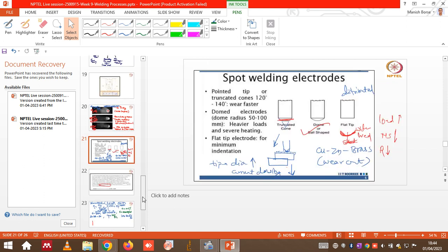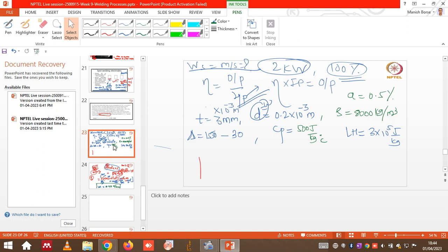In most cases, only volume is important, because of how we have to manage the volume calculations. Sometimes they already give volume or energy in joule per mm cube or joule per meter cube, like melt energy, where we have to multiply it with the volume. But in certain cases they give cross section area and we don't know the thickness, but welding speed is one of the variables, just like in this numerical, with unit mm per second.